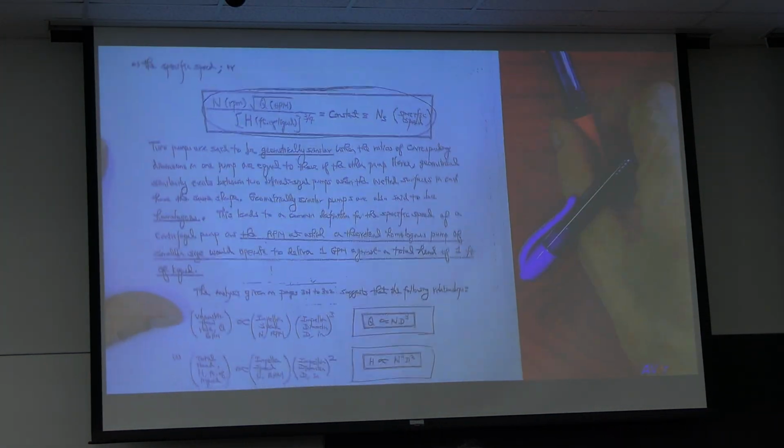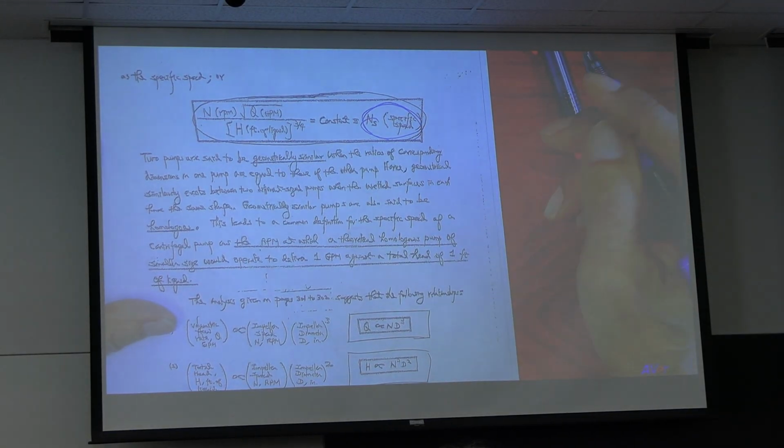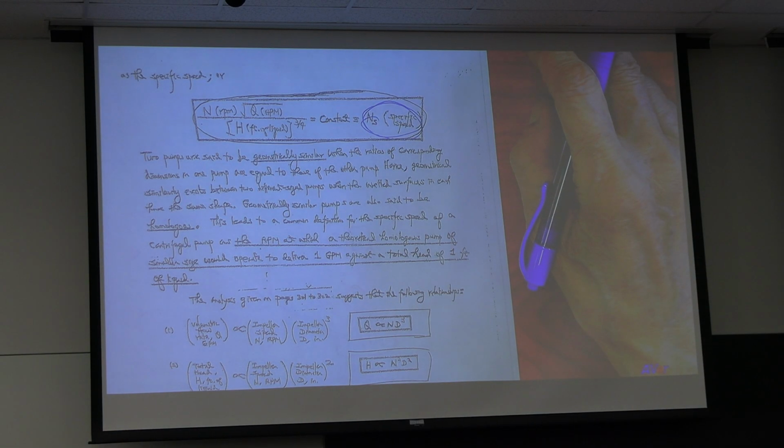So, on page 303, specific speed, depending on the value, less than 8,500, between 8,500 and 12,000, above 12,000, it determines whether you can buy the pump.